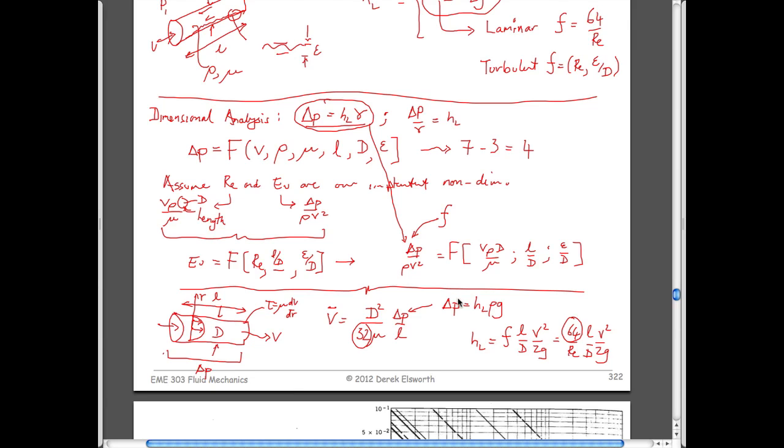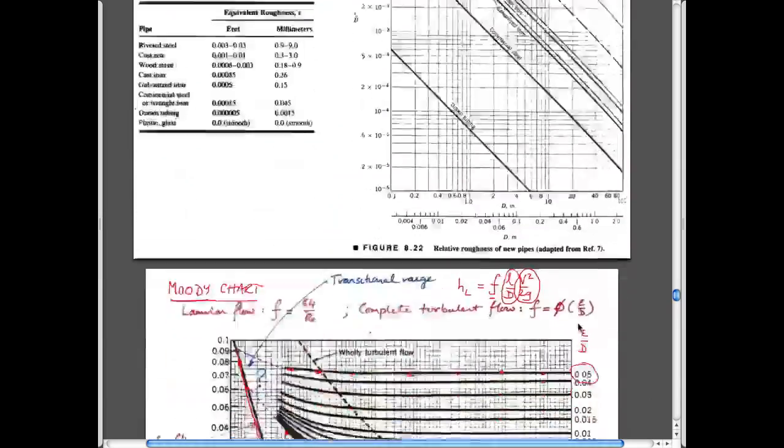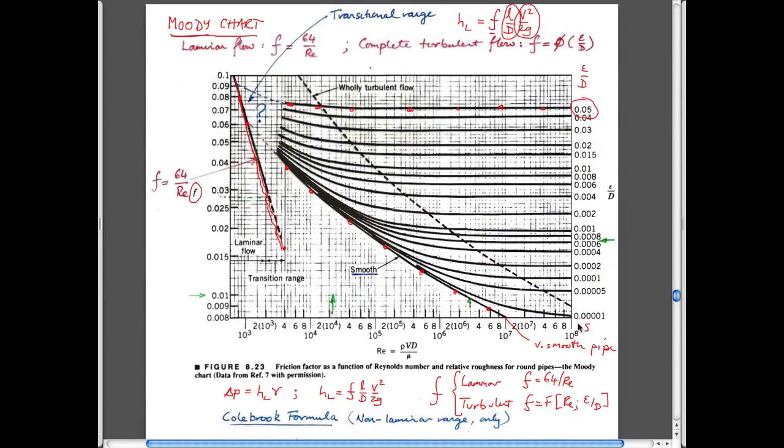And so merely by taking this solution for laminar flow in a pipe, we end up getting this magnitude for the friction factor, which we called lowercase squiggly f, which is exactly the gradient of this line here. And so that's exactly where it comes from. So there's no particular magic in that. It just comes out of the very simplest case that we can evaluate behavior for.